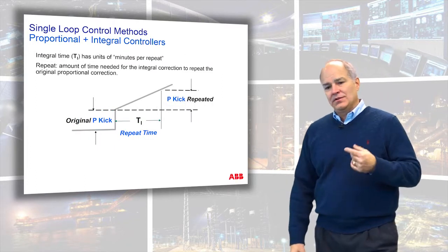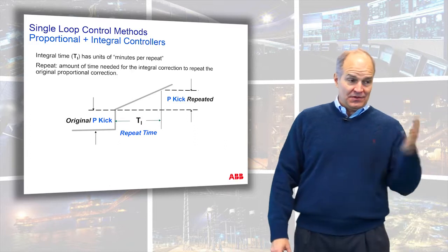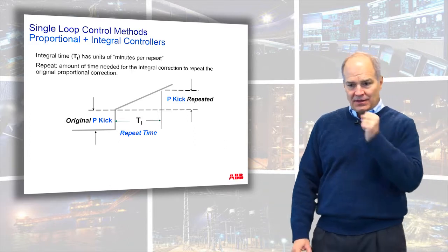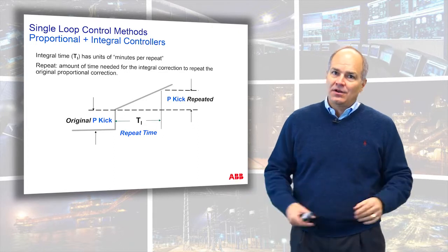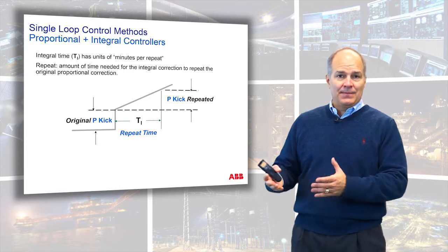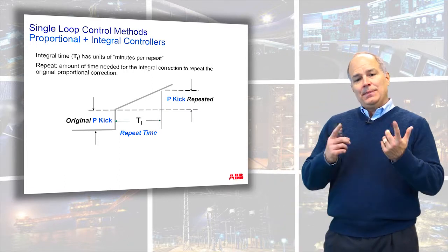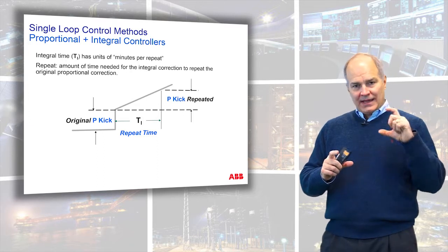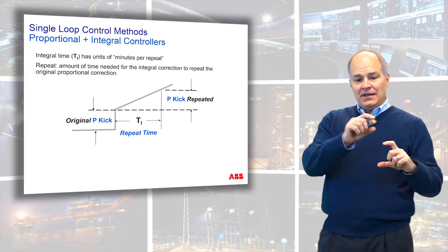So we're going to talk about that, but this is an actual real picture that you can get. Now, when you hear the term reset time, that was confusing for a long time. A lot of people said, oh, reset, that means I do nothing and then I reset. That's the wrong interpretation of reset time. Or repeat time: well, what in the world am I repeating? Well, when P and I are working together, your proportional kick happens when you have a step error. Then integral takes over.